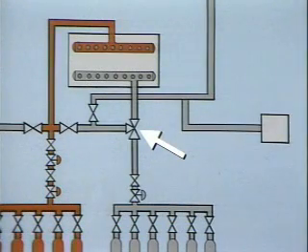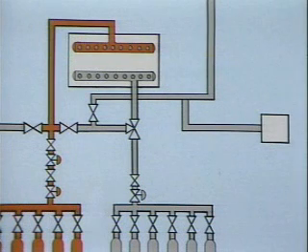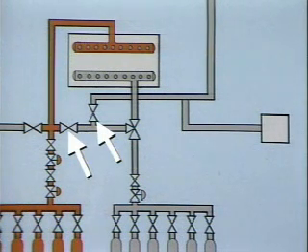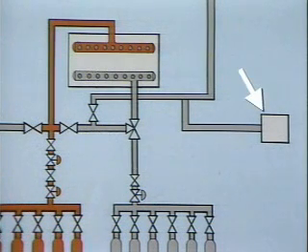A three-way valve is used to control the flow of all three gases, hydrogen, CO2, and air, that will be used in our purging example. Vent valves control flow through the vent pipe. A gas analyzer is connected to the vent pipe to provide a means of monitoring the purging procedure.